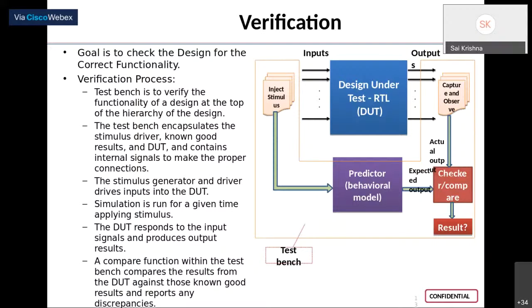And when you actually test it using Cadence tools, you will get a certain waveform or a certain value. Only when both of these, your prediction as well as the actual value after simulation, are the same, to be precise, exactly the same, can you go ahead and proceed with synthesis. But if your captured values and your predicted values are not the same or they have a certain deviation, that means there is some fault or some problem with your program.